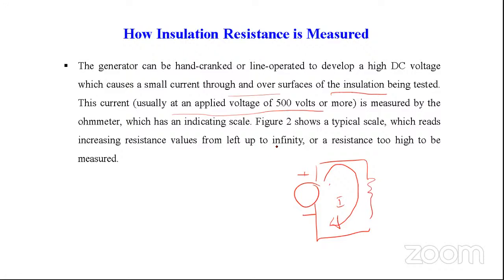All of you may know that if you want to measure the insulation resistance of an insulating material which operates at a very high voltage level, then performing the measurement at a very low voltage level doesn't provide a good result. After application of the applied voltage, certain general phenomena occur inside the insulating material, and these basically govern the insulation resistance.